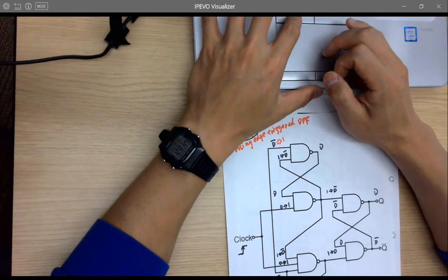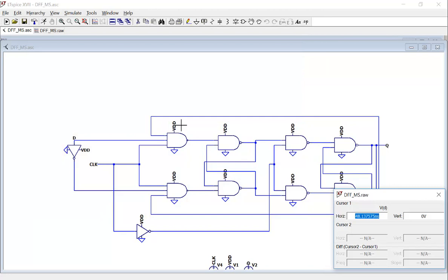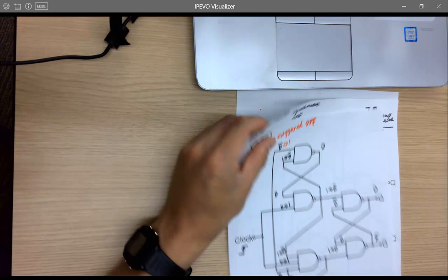So the SR flip flop is what? It's a level trigger. So no matter what is changing at D, when clock is high, right? When clock is high, no matter how D changes, it's going to send the signal to the middle place here. That's storage for D temporarily. Does that make sense? So the SR flip flop is level triggered. How to control it? Make it edge triggered? There's no way to do it. So if you want to make it a rising edge triggered flip flop, you need this, right?